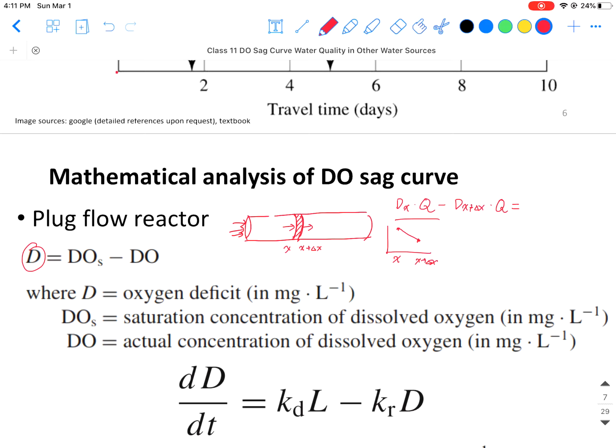The rate of the reaeration is higher compared to the rate of the deoxygenation, right? So then we can write out the other terms, which is Kr multiplied by V, okay, and also multiplied by the oxygen deficit that's within this thin slice here.